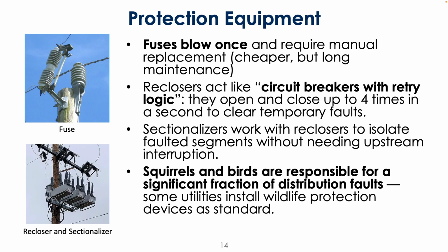I think most outages are wildlife related. Yeah. So with utilities, there are a number of things that can cause these issues. There can be weather-related events, like high enough winds knocking things into your lines, or even, though this is a lot rarer and usually happens in more degraded lines, if there's enough droop in the lines, they may actually swing together. So things like that happen.